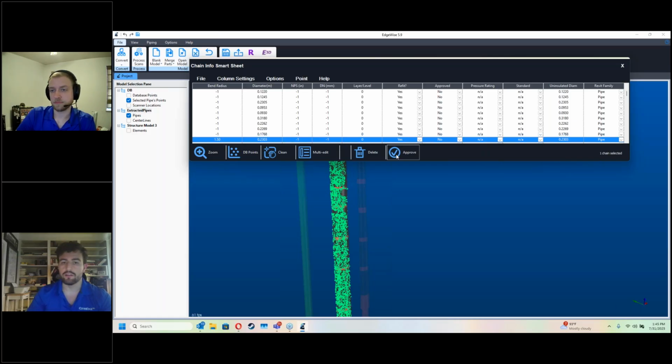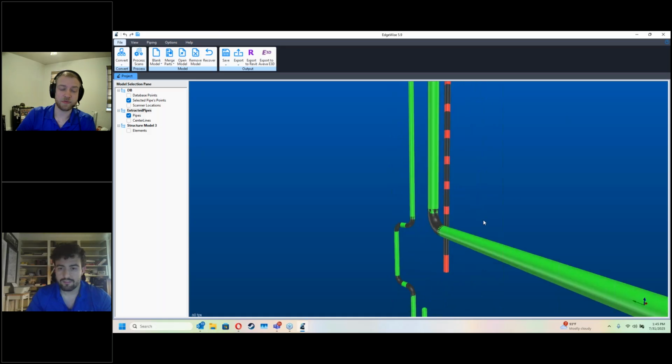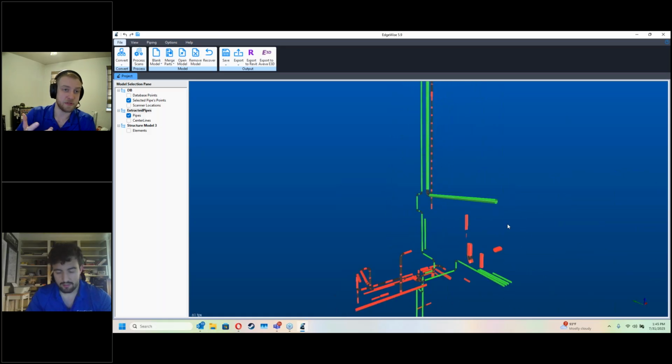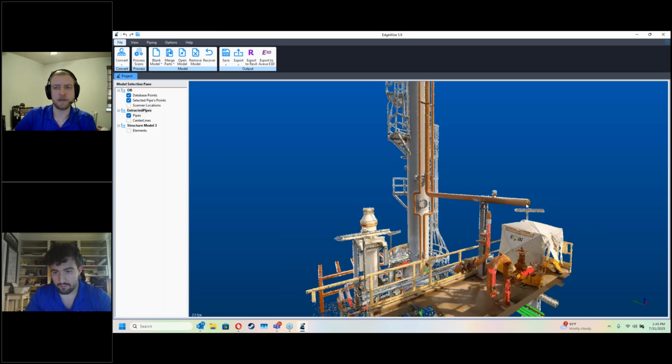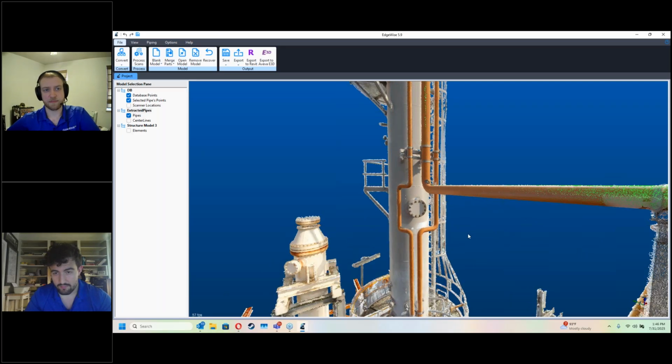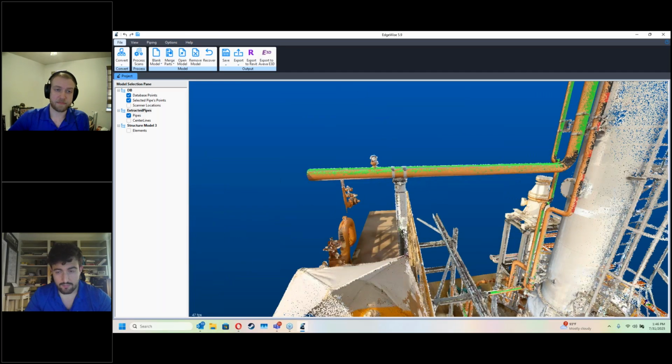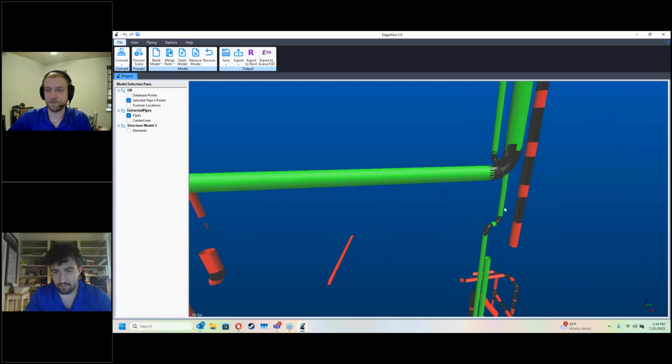If I remember correctly, if you're a Leica user, you can download it, or actually anyone can download it. Yeah, it's free. That should be able to bring in the 3D geometry. I think they dropped support for AutoCAD last year or the year before, I can't remember off the top of my head. So STEP is the general recommendation for AutoCAD, but I believe MicroStation still uses that, though I'm not 100% sure on that.